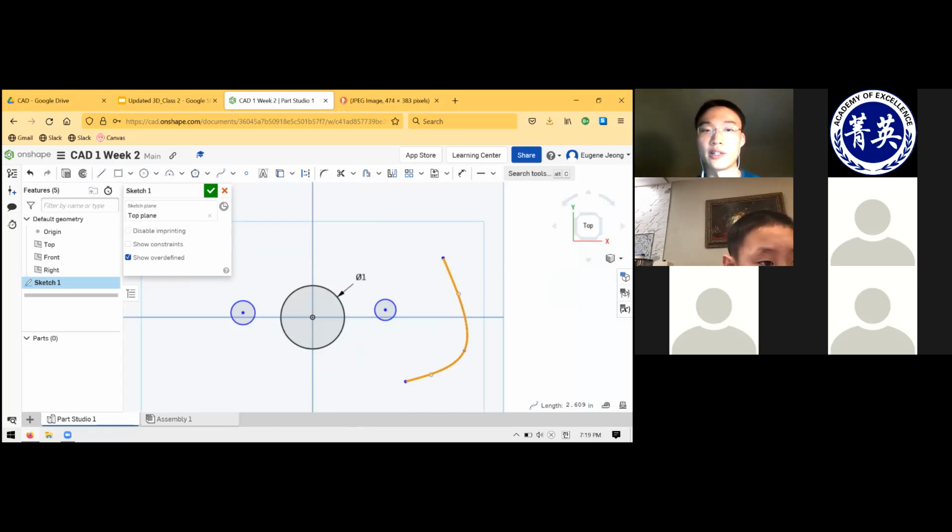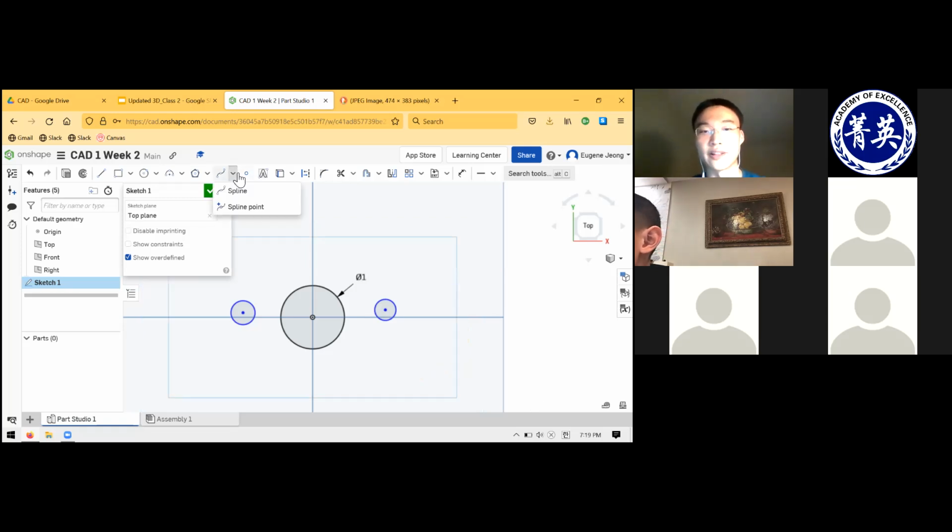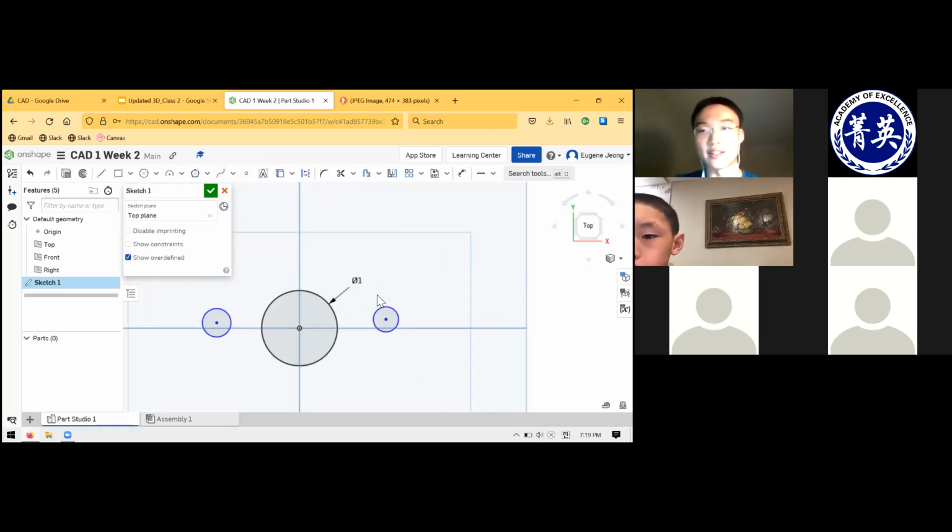And the other one is where you're trying to fit a curve. So in some applications, for example, properly done gear teeth, you need to follow a mathematical curve, like an involute. And in those cases, you might have an equation-driven curve that you try to fit a spline onto. But for most cases, I would recommend not using a spline just because it gets out of hand very quickly.